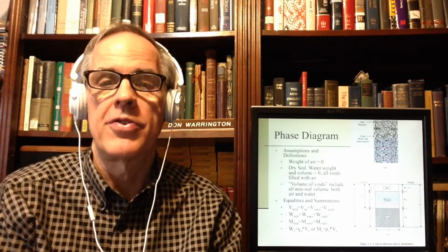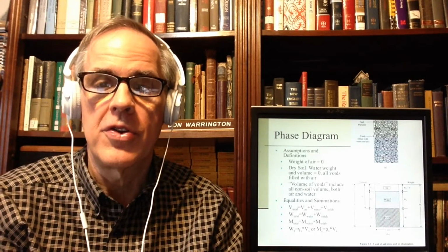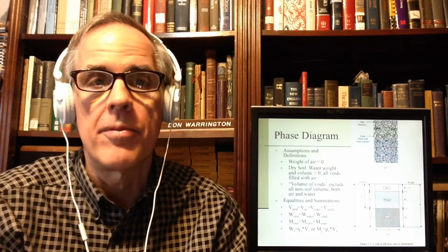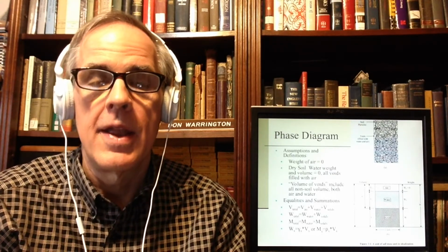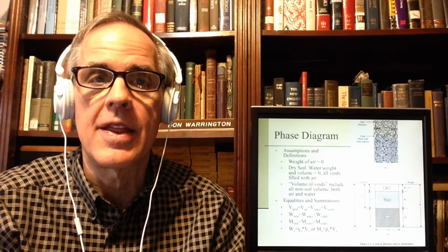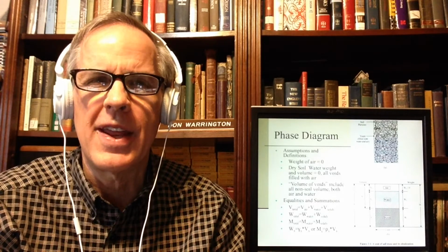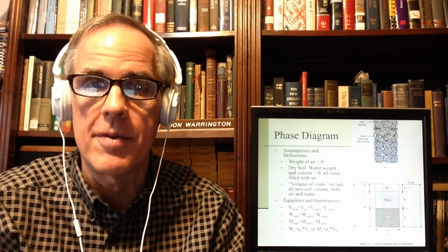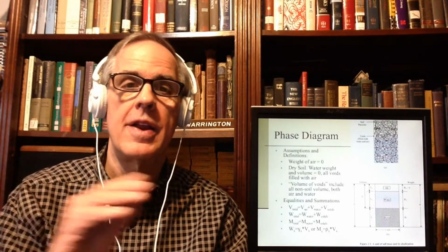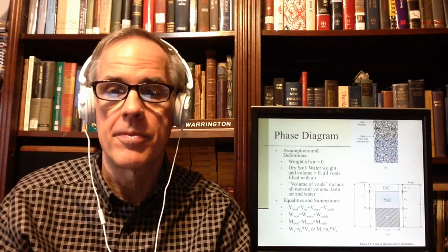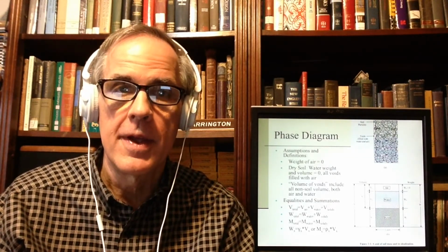Second, in a dry soil, there's no water at all. In completely dry soil, all the voids are filled with air. Now the voids are anything that's not a solid particle. And we must remember that we would think, void means air. Void does not mean air. Voids is anything that's not solid. So voids can have water, they can have air, they can have some of both. All the volume of the voids, they take up volume, and they have weight.